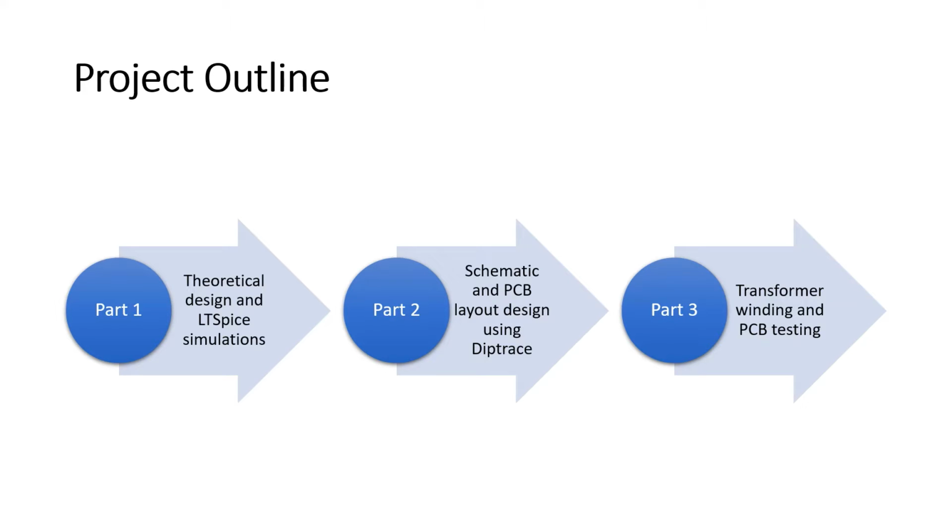In the first part, we perform the theoretical design, decide on the component parameters, and run LT-SPICE simulations to verify our design. In the second part, we draw the schematic and PCB layout using the DipTrace software. And in the third part, we receive our actual PCBs, solder the components on them, wind our transformers, and run tests on our finalized flyback converters.